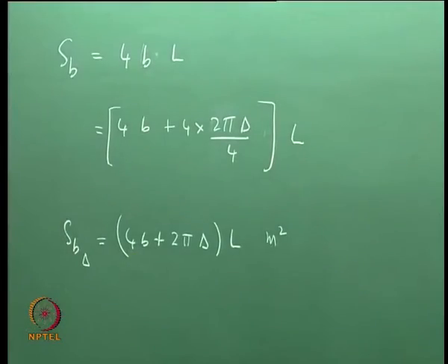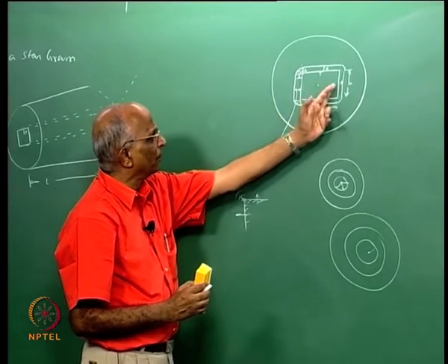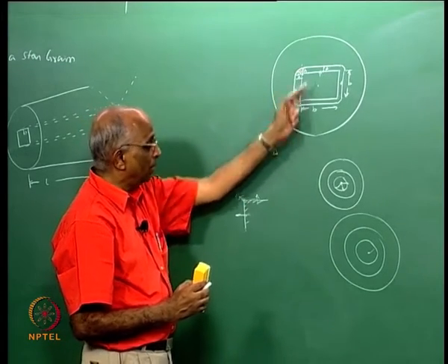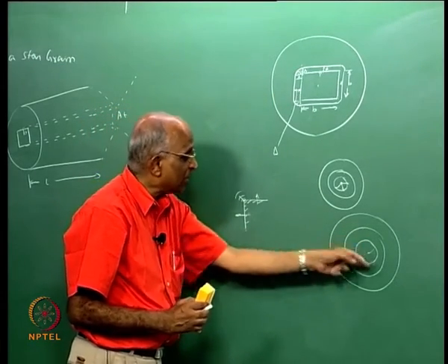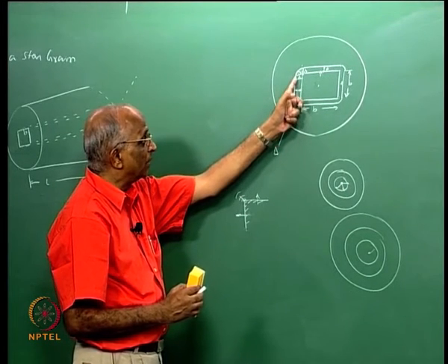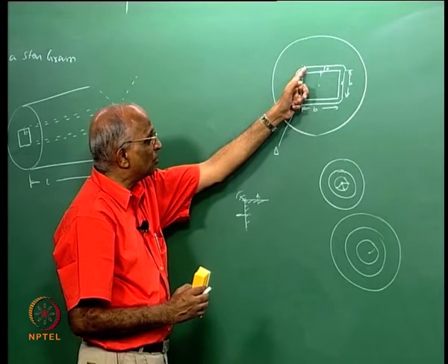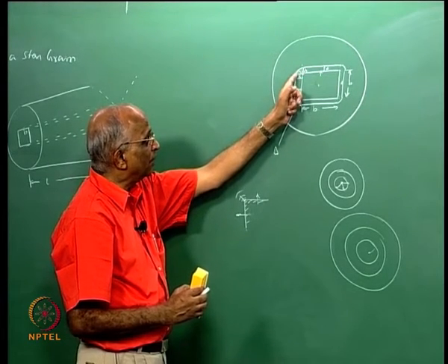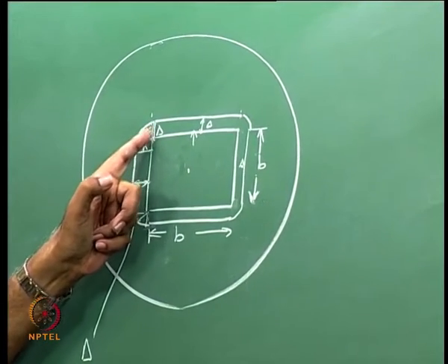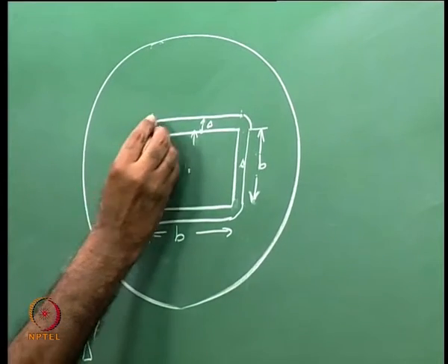I think we should try to understand this. All we are saying is, if I have something like a square with a vertex over here, the vertex burns being a point, so it evolves as circles, but this surface evolves as a plane because burning is normal here. Therefore, as the vertex burns, it meets these two surfaces here. Therefore, I have a quadrant, and the perimeter of this quadrant is 2 pi into radius, 2 pi delta, divided by 4 is the length of this quadrant, let us say from 1 to 2.